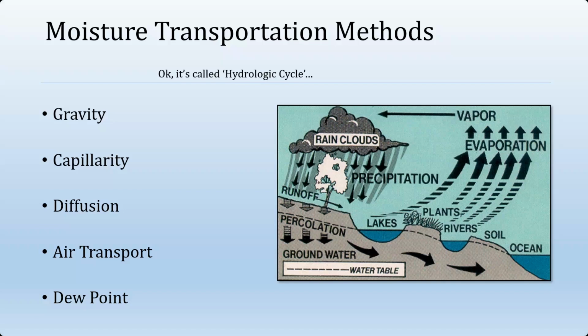Diffusion of water vapor in the form of a gas is, in my opinion, probably less of a concern. It's certainly not anything that we want to dismiss altogether, but I think some tend to get a bit super focused on this. To me, the biggest enemy of moisture transport is bulk air transport. Frankly, I refer to air transport as a hole in the wall, or the failure to properly flash any of the penetrations or rough openings. And dew point is something that I think is sort of akin to diffusion with regard to how moisture gets into or out of a structure.